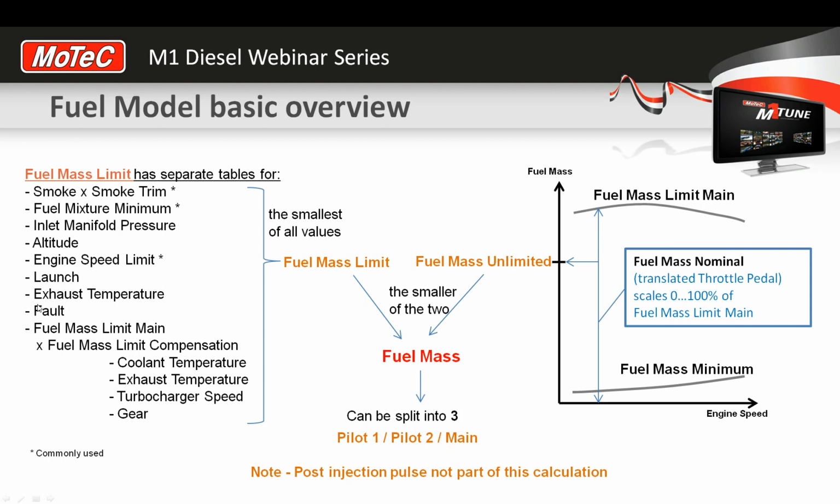Then any of our faults that occur, so if we have an oil pressure fault, any faults that we choose to, we can have that fault condition actually remove fuel. We can have 50% of the power reduced if something goes into error, to tell the customer there's something wrong and they need to pull over and get it fixed.